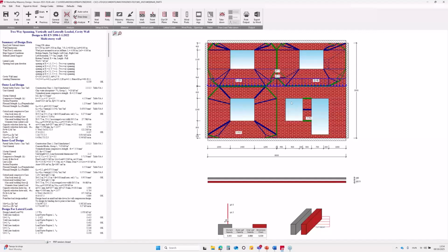both a ground floor and a first floor with horizontal lateral support provided by the intermediate floor level and the vertical support, representing the effect of an internal return wall. The program automatically divided the wall into 4 analysis zones and performed independent yield line analysis for each one, providing a realistic representation of the wall's true behavior.